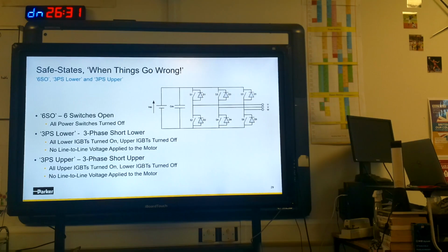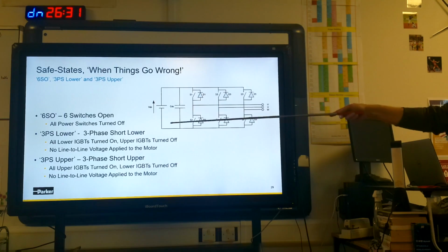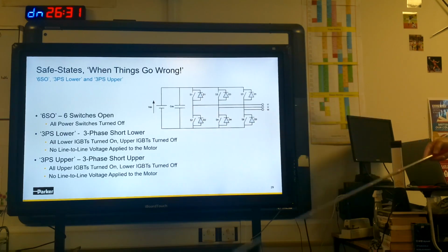That's okay. Let's play that game again, but let's say this time I was operating just into field weakening and I had my thermal trip on my motor. I turn everything off. Well, now my back EMF is bigger than my battery voltage. And I've got a 3-phase rectifier through these freewheel diodes. So what happens is you start to rectify the back EMF, you get uncontrolled current flowing back into the power converter into a high voltage battery. That means I'm doing work. So that translates as lots of braking torque on your motor.